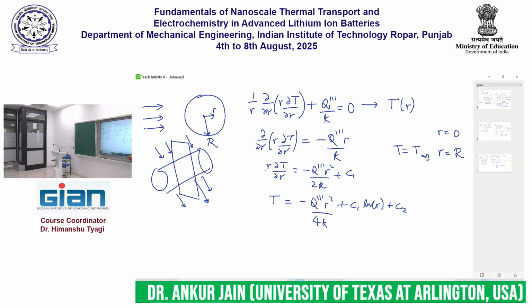Right? At r equals 0, the gradient should be what? The gradient should be 0, yes. Or I can make a mathematical argument that log of 0 is not defined, right? Therefore, in order to have a realistic temperature at r equals 0, I must choose c1 to be 0. So c1 must be ruled out in order to ensure a finite reasonable temperature at the center of the cell.